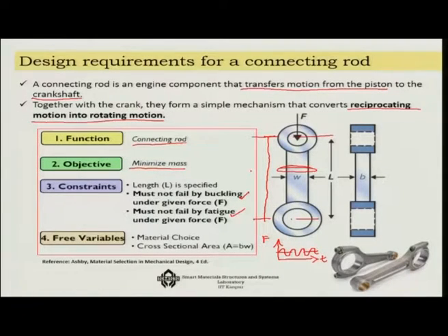Now, you may see that the actual connecting rod has a couple of additional things. For example, it is not exactly uniform, and secondly it may also happen that certain masses are scooped out from the system. These are the two strategies that are taken. One is in terms of controlling the natural frequency.